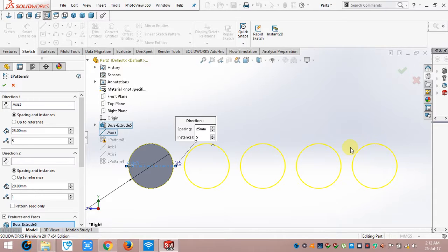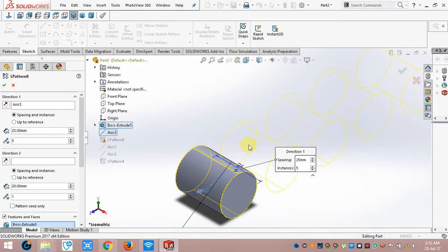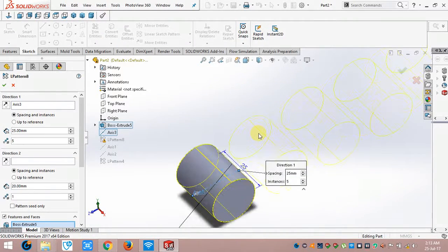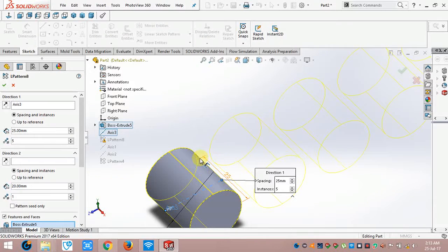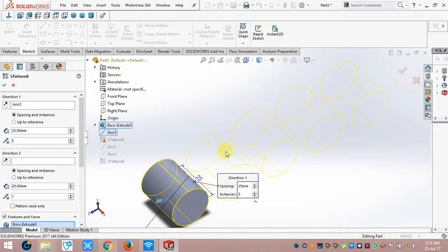disjointed, because if I go to the 3D view, we can see that this element and this element are not actually jointed by any material or by any plate. So if it isn't jointed, then I can't actually apply the spacing between these elements to make it a 3D linear pattern. Yes, in the preview we had the linear pattern with the spacings, but it's basically a theoretical thing.